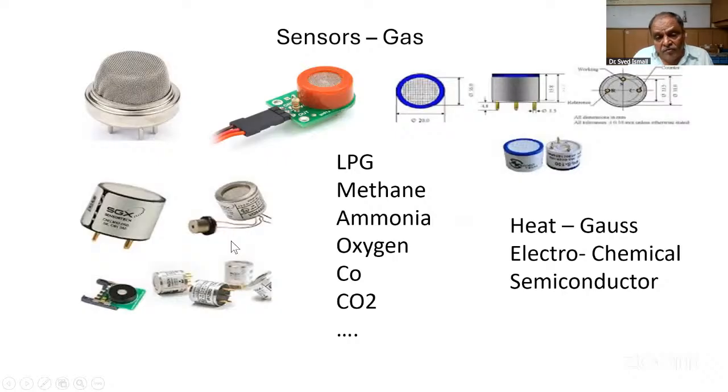And you use a lot of gas sensors. For example, I used them for onion storage. We tried different gas sensors, for example, to measure methane released by paddy fields, or whatever gas you want to measure. In polyhouses, you want to know how much gas there is. These sensors are readily available. You must know what sensors are available and what accuracy they have. You can easily find almost all types of gases. But remember, certain gas sensors like CO2 sensors don't last very long.